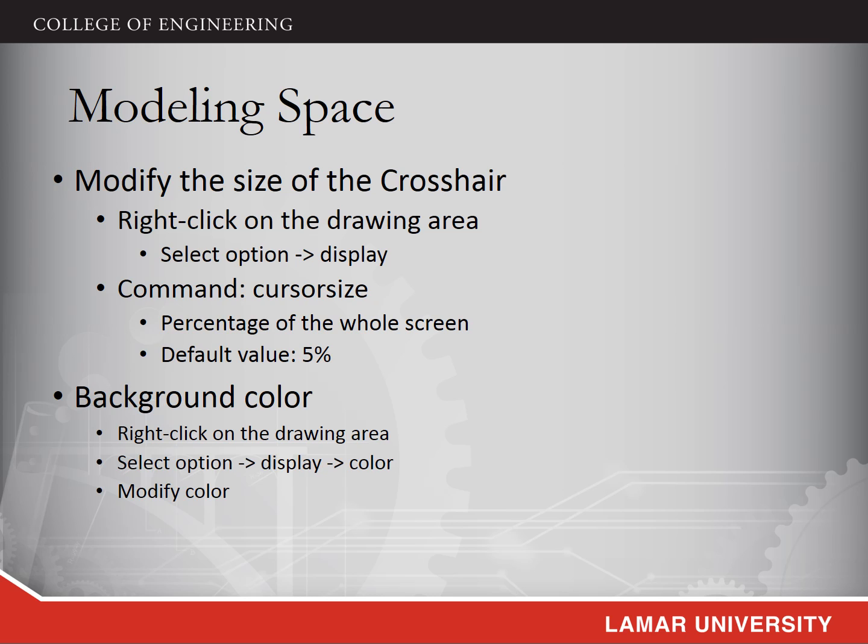To modify the background color, you can also right-click on the drawing area, select the option display and color to modify the color of the background. In the next slides, I'm going to show a demo about the modification of these two properties.